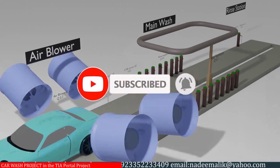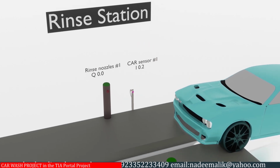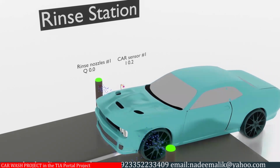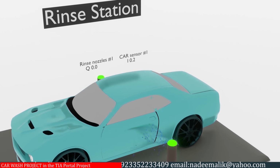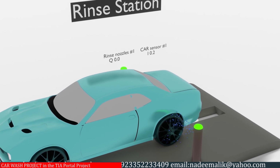At the rinse station, we have a car sensor number 1, which is connected at the I0.2 input of the PLC. When the car comes in front of this sensor, the PLC will turn on the rinsing nozzles by turning on the PLC output Q0.0, and the rinsing nozzles will spray water on the car for 50 seconds.